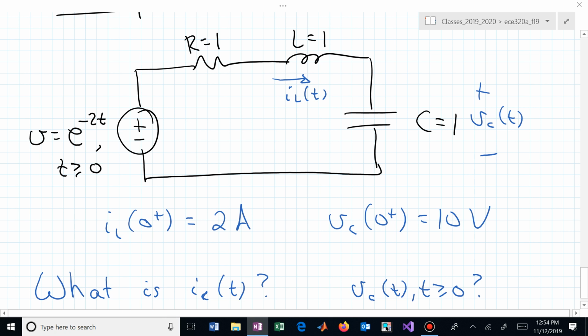Which one can you always be assured will be applicable? Both? Node voltage? Do I have the third option? Mesh doesn't work with non-planar circuits. This is a planar circuit. I don't have wires crossing. Node voltage analysis always works. So we can always use node voltage analysis. We kind of like to always rely on our old standby, which is mesh analysis, but just letting you know, sometimes you do have to apply node voltage analysis.